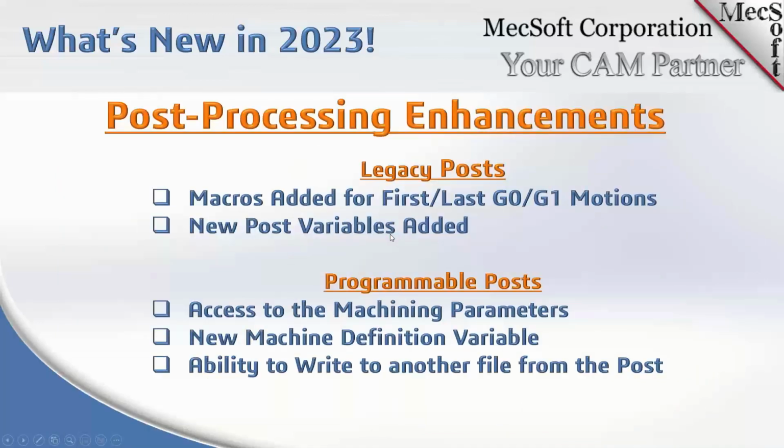Now we're doing some post-processing enhancements as well. Joe, you want to handle this one? So as far as post-processing enhancements, we have segmented that into changes to the legacy posts and then the programmable posts. So we've added macros for first-last motions. We've also added new post variables based on user input. And then in the programmable posts, we have access to the machining parameters now.